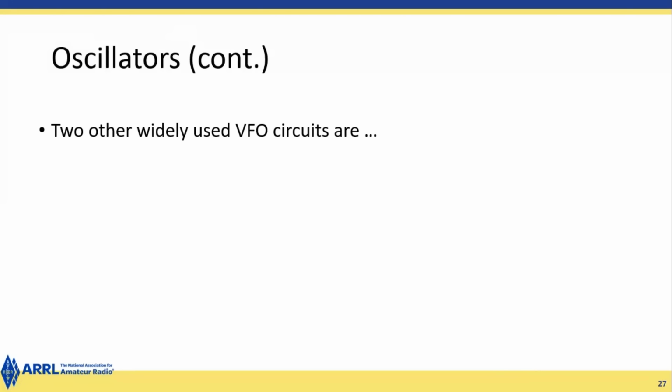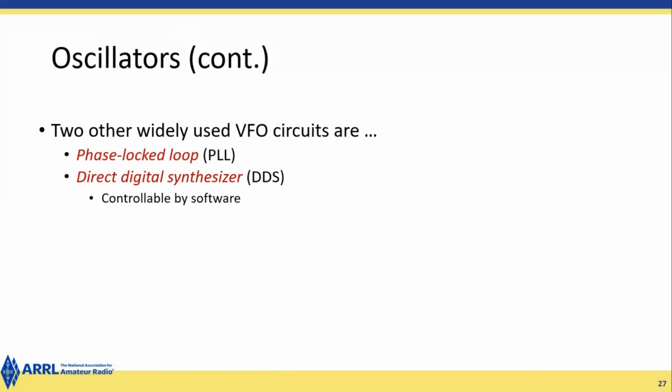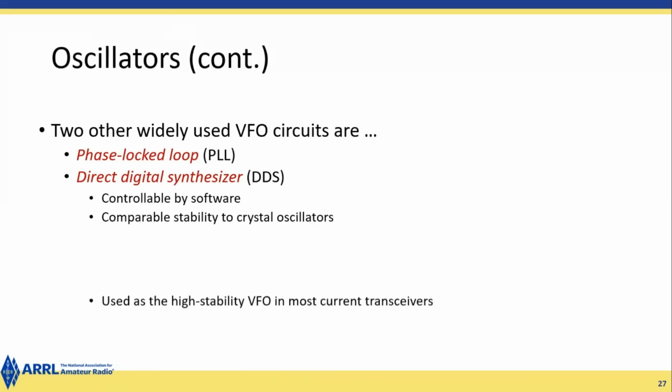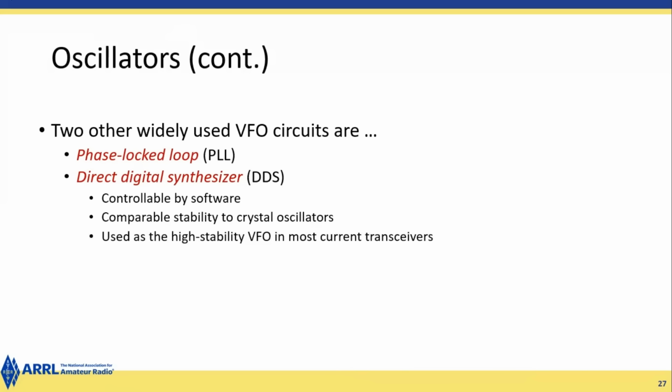Two other widely used VFO circuits are the phase lock loop, PLL, and the direct digital synthesizer, DDS. The DDS is controlled by software. It's comparably stable to crystal oscillators, and is used as the high stability VFO in most current transceivers. Most of them have a DDS in them these days.